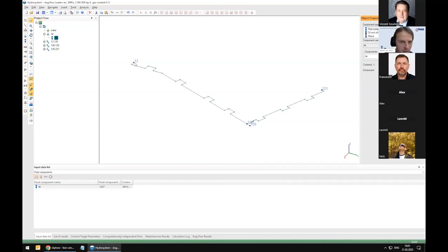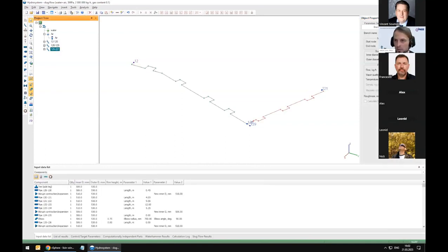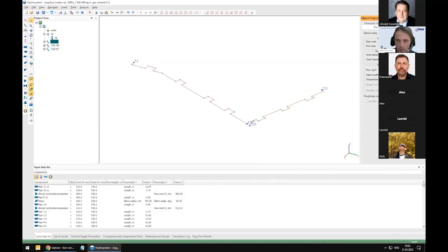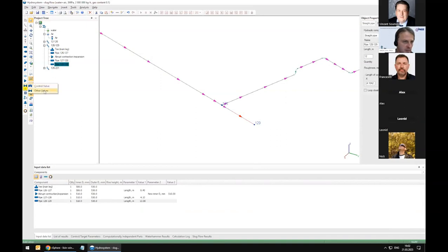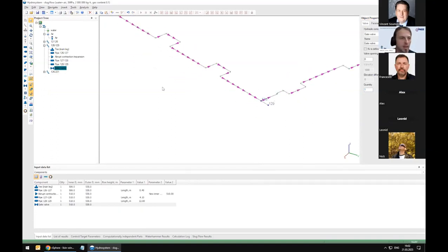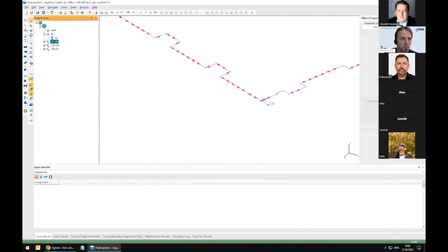And let's say that our initial pressure over here is about 3 megapascals. Our flow rate will be about 2,000 tons per hour. And our gas to liquid ratio, let's say it will be 10%, something like this. And we're going to close this one over here. Going to add some closed valve here, so there will be no flow in here. Okay, oh sorry, 0.1. So that's it. We're ready to perform analysis.